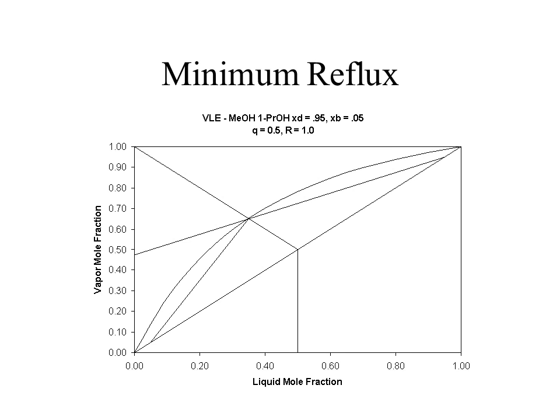There is a minimum reflux ratio that is achievable in a column. In this case, we will look at a system like before, but let's draw our upper operating line where that intersects the Q line right at the equilibrium curve. And this is the case where R is equal to 1. If you try to step off stages on the upper part of the column, you will find that you would get pinched in right at that intersection point.